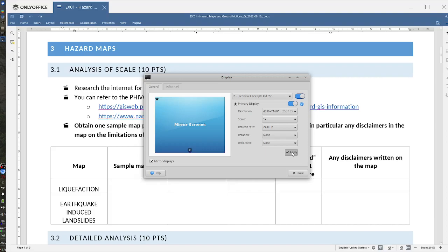So 5.08 plus 1.16 multiplied by the log of the surface rupture length. This will be log 10. Then log 10 is just 1. And then you finally have this quantity, 5.08 plus 1.16, that will be 6.24 moment magnitude. So that's how you can use the Wilson-Coppersmith equation.